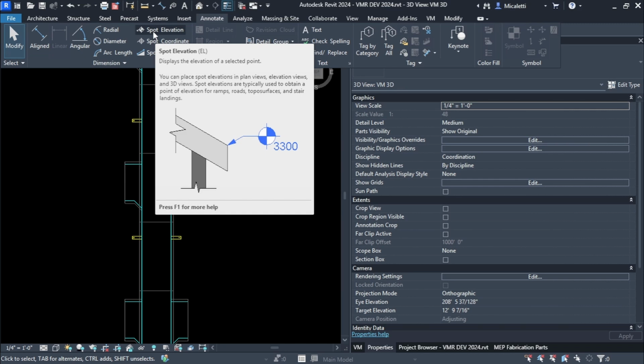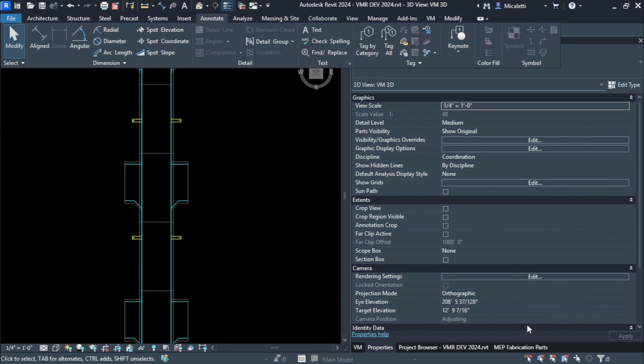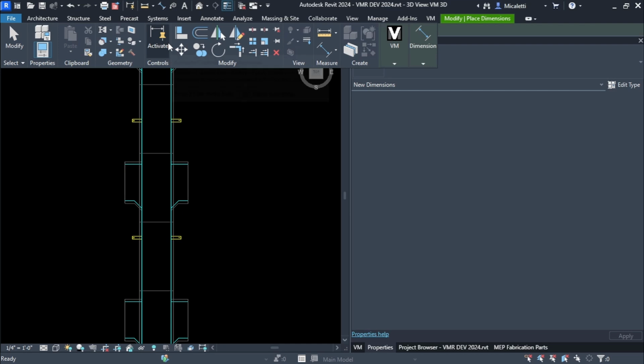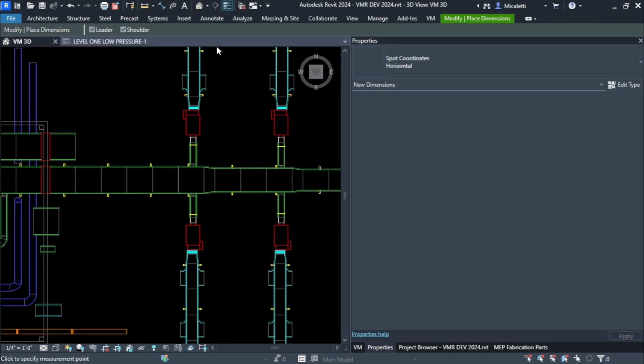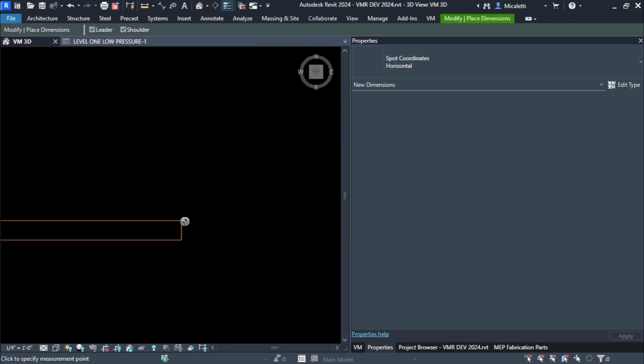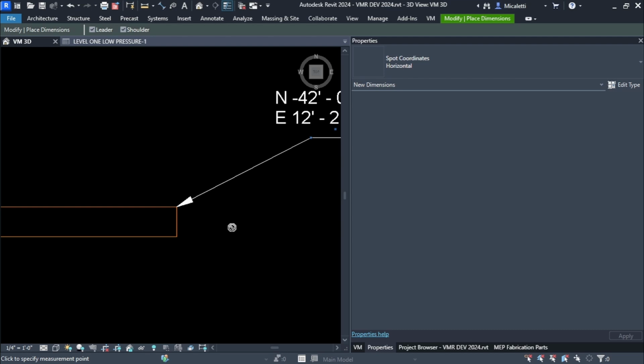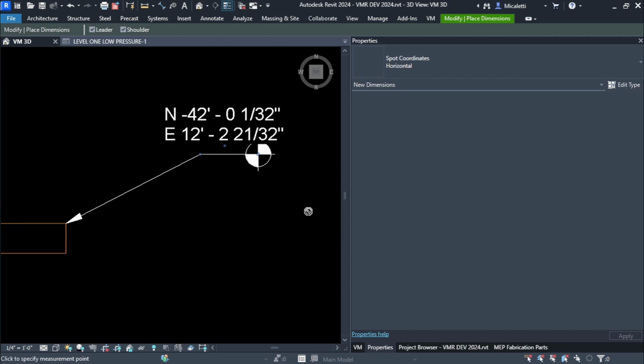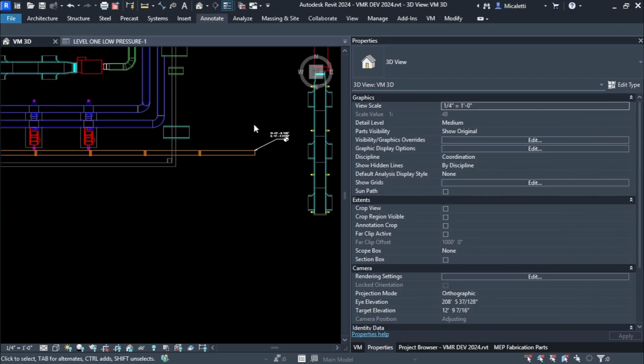It also gives you a lot more flexibility in that you have all the power of a Revit schedule and all of this data. But here you have coordinates. So here's a way to verify your points just out of the box. Not necessarily tagging them, but you're making a schedule and you want to spot check a few points. You can do that.